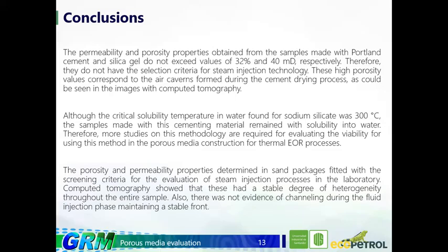And the last one could be that the porosity and permeability properties determined in the sandpacks fitted the screening criteria for the evaluation of this steam injection process in the laboratory. The computed tomography showed us that we have a stable degree of heterogeneity throughout the entire sample, so it is not a homogeneous sample, and this is important for representing the heterogeneity that the Colombian reservoirs have. Also, there was no evidence of channeling during the fluid injection phase, maintaining a stable flow in all the sample core.